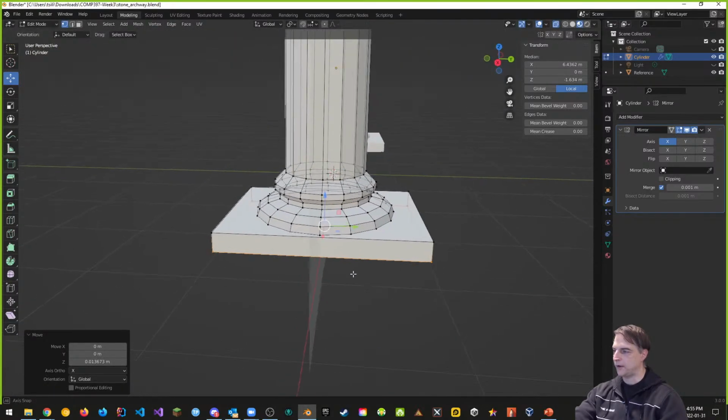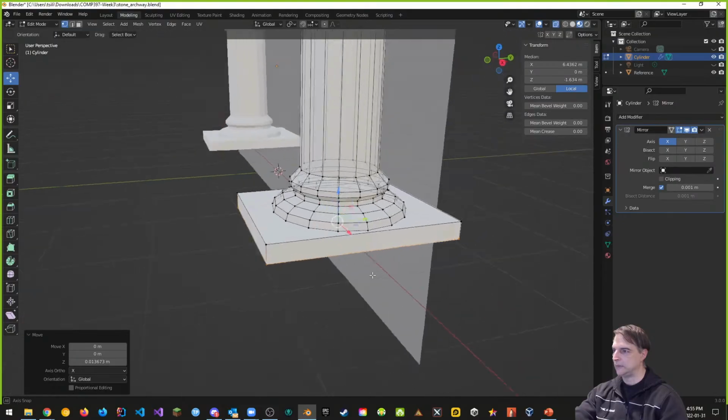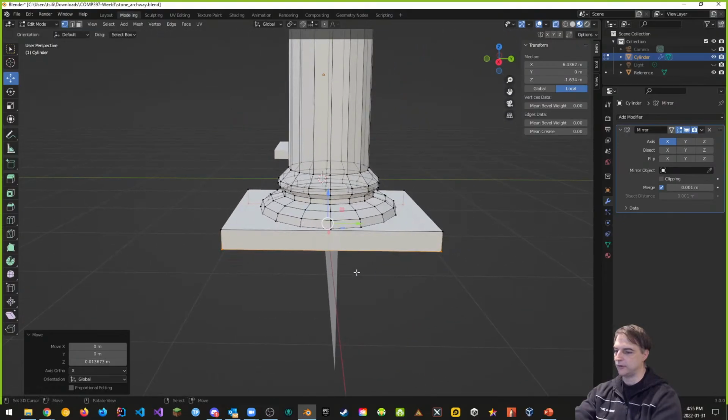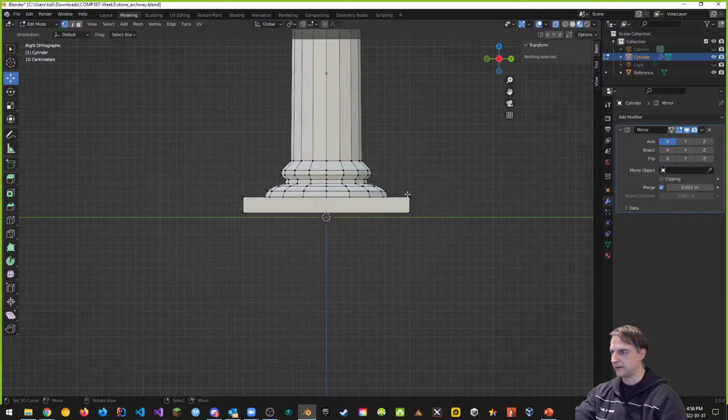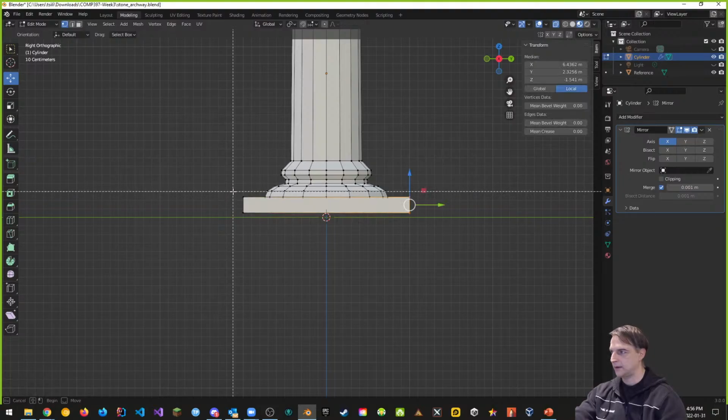All right, cool. So that's our box, but it looks really big on the sides. And I think what I want to do is just move to the side view for a second. On the side view, we don't have a side reference, but we're going to bring it in so it's proportional like we saw it. So I'm going to select both this side and this side, and then just bring it in.